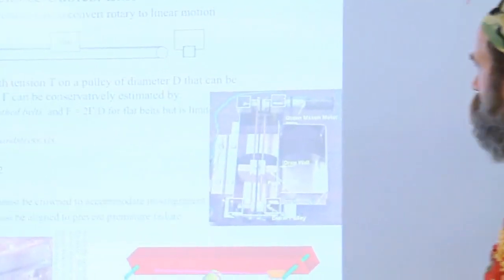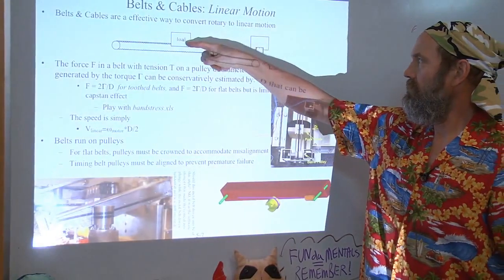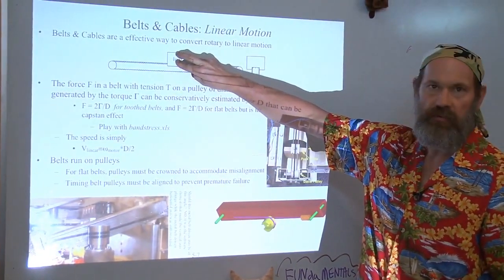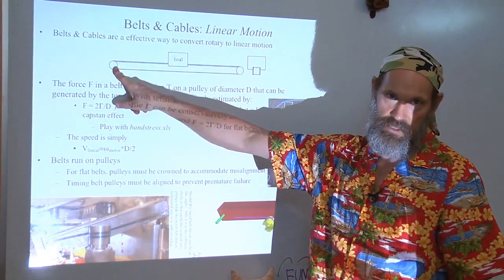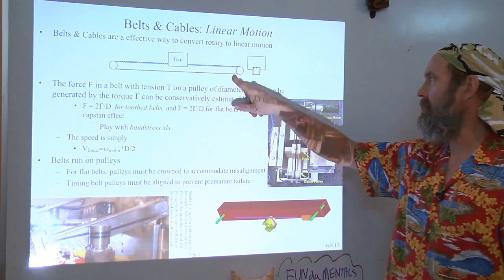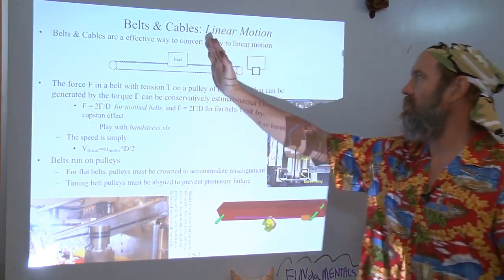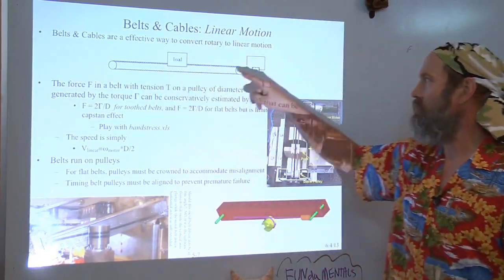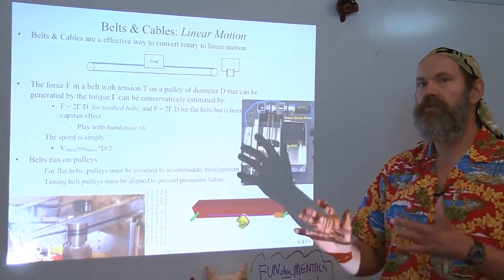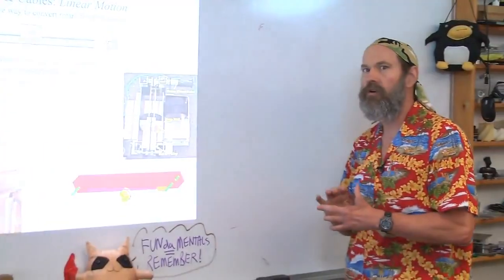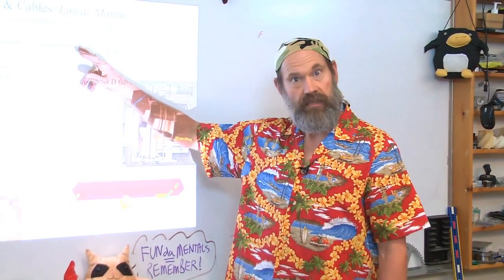What the belt allows you to do, have a motor, belt which is attached to the load, which is then supported by a bearing, for example, linear bearing. The belt continues around a pulley at the end. This is an idler pulley, and back. So boop, boop, boop, boop. Motor moving back and forth real fast here causes the load to move very, very fast. And you do this, the belt has very, very low mass, hence very low inertia, so the systems can be very, very fast, even though they're based on really old, boring, low-cost, robust technology.